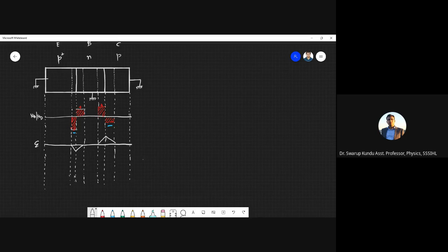Now let's draw the interesting part, that is your band diagram or the E-k diagram we popularly call, right? So for E-k diagram, what we first do is, again let me just clarify. So this region is our neutral region in the P plus, and in the base, let me put a color.